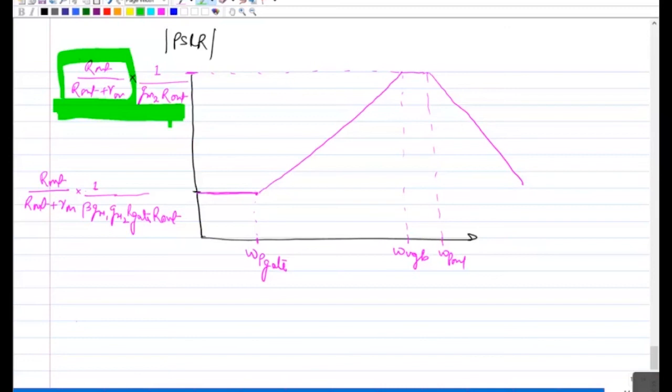If you are getting, let's say, minus 60 dB in PMOS, then you would get roughly minus 80 dB here in NMOS. So both DC and high frequency PSRR look better in this case. Any other benefit do you guys see? Can anybody tell, is there any impact on UGB in the NMOS compared to PMOS?